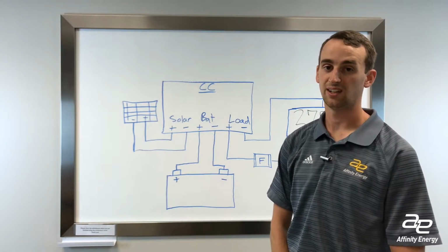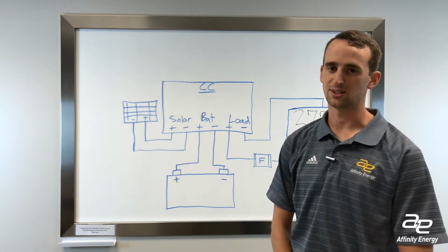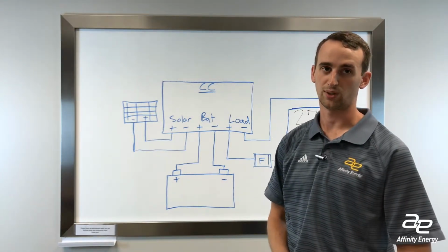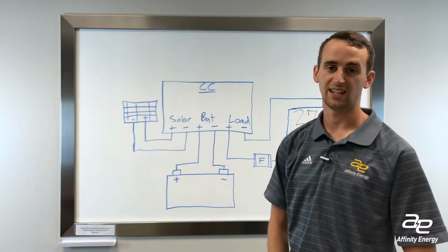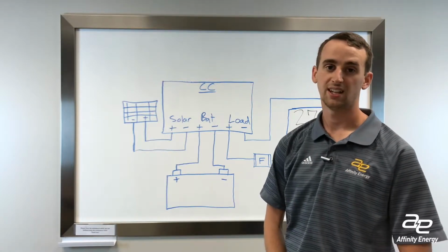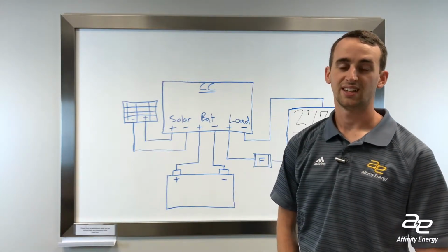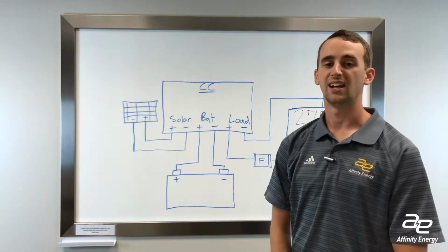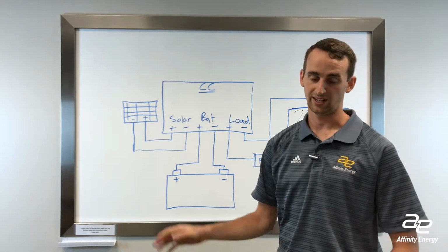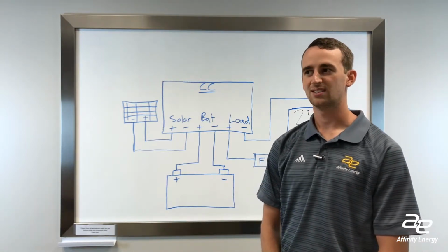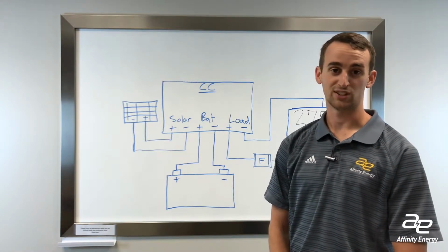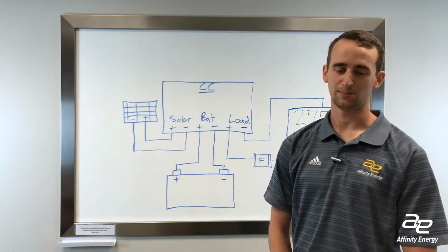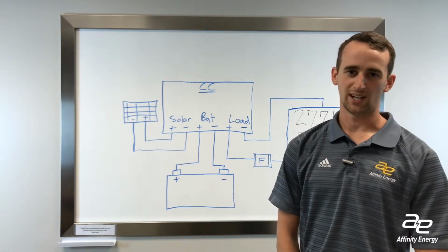So most likely it's probably going to be two 12 volts. So for our design, we're going to look at lead acid gel and AGM technologies. And these are good because they don't require any maintenance. They can be mounted upside down because there's no free acid within the battery, and they can be deep cycled so that if there's rain or clouds for many days, or if there's an eclipse of the sun, then it should be able to handle it depending on the amp hour rating of your battery.